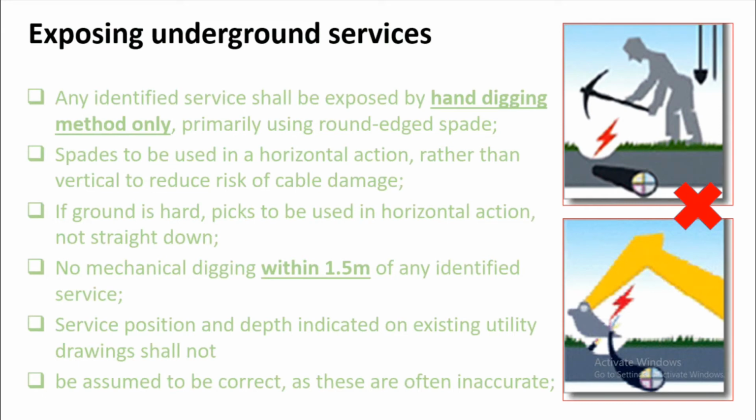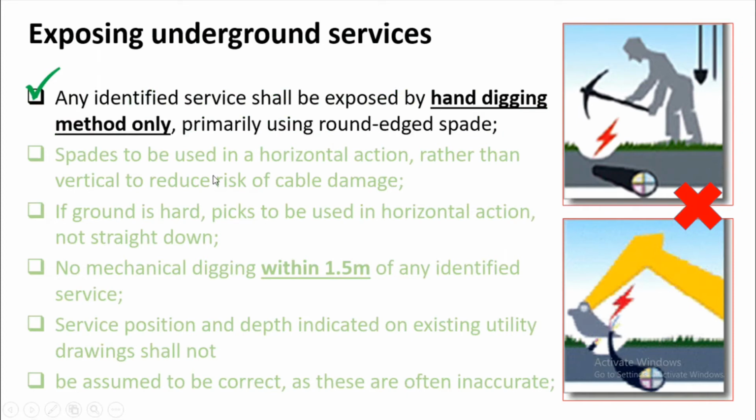Exposing underground services. Any identified services shall be exposed by hand digging method only, primarily using round edge shape spades. Round edge spades. So don't use pointed ones, as you can see in the photograph on the above right. They are using the pickaxe. This is very dangerous on underground services.